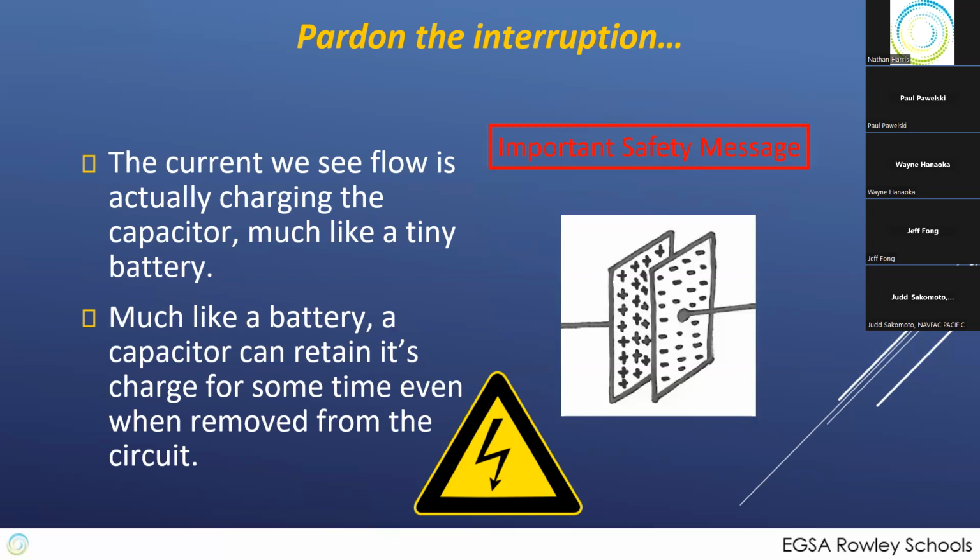Here's the thing, though. When we close that circuit, those electrons are all still sitting there, which means it's retaining its charge. If you've looked at the plug-in for your laptop and the little green light on it, when you've unplugged that from the wall, the light doesn't go out right away. It slowly drains down, and that's because the capacitors in the system are still holding power. And while it's not that big a deal if you touch the ends of the plug on your little power supply for your laptop, it can be a big thing when you're looking at the capacitors on a control system.